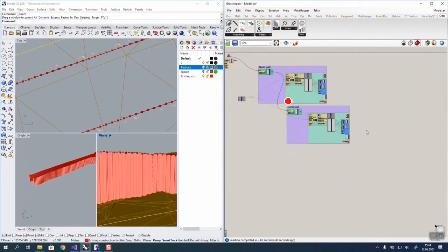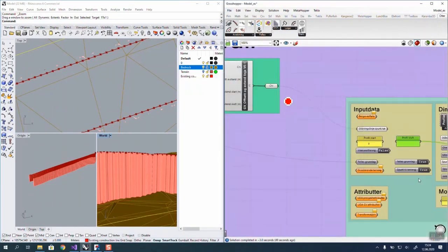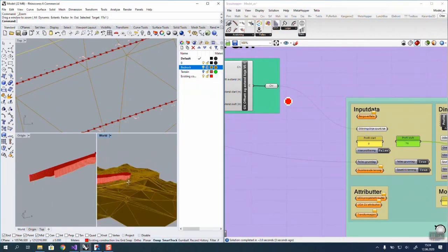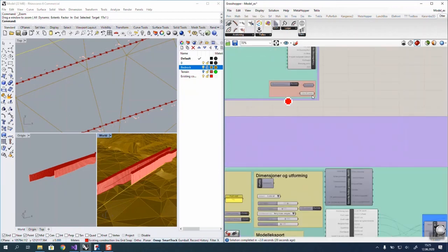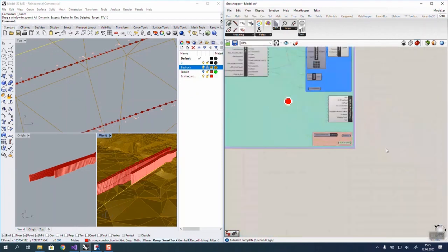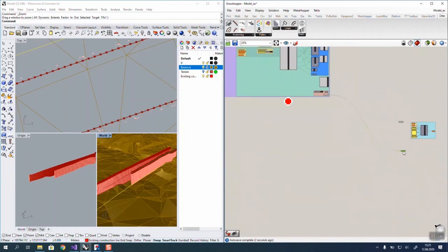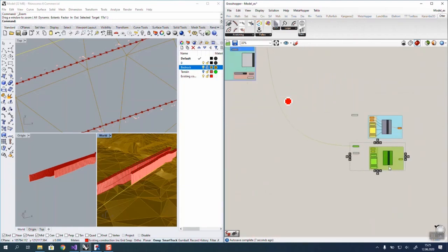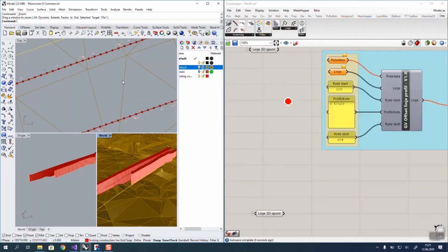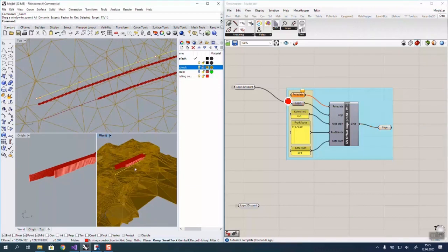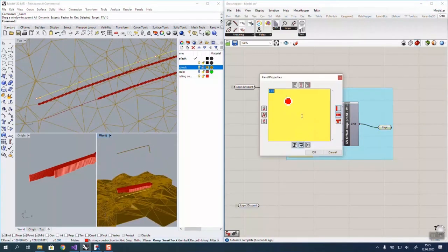So let's model some struts as well. For this, we need the lines coming out from the sheet pile script and connect them with another offset script where we can specify if the struts should be on a specific contour. Just have to take out the lines here from both walls, of course. We need the struts to go from the north wall to the south wall. So if you connect this, and here you see those little scripts for adjusting the lines.